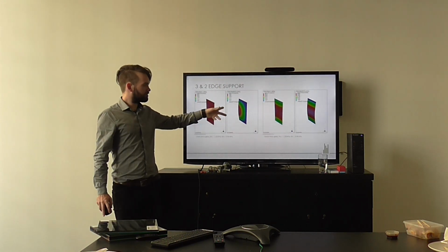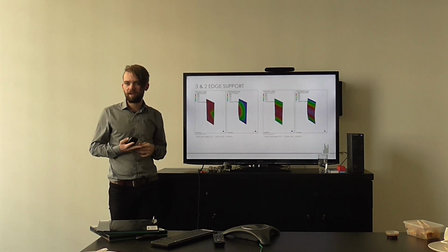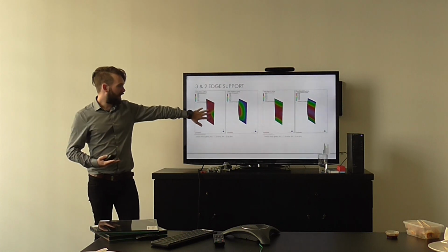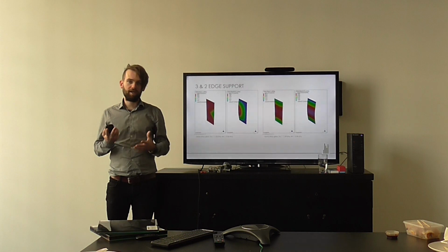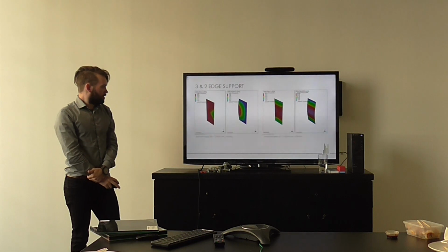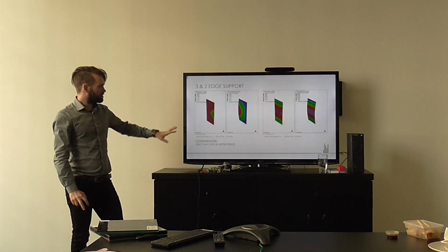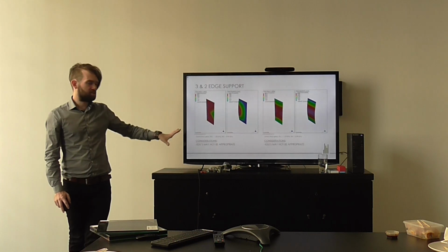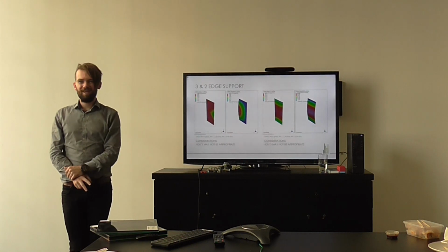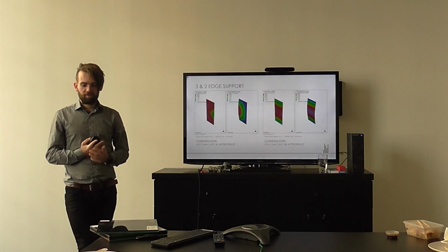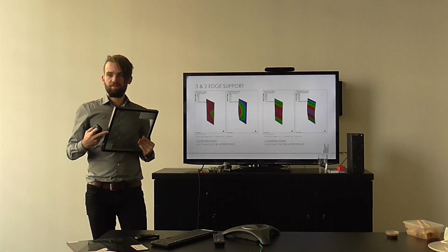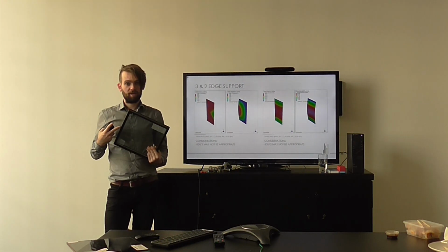The next one we move on to is 3-edge and 2-edge support. Now, these situations come up more probably in your lift lobby kind of areas, usually at a corner junction where you don't have a corner mullion, or you don't have, in this case, glass fins, and you want to read floor to ceiling glass. So what the considerations are here, we'll start with the 3 edges. In both of these situations, IGUs, meaning insulated glazed units or double glazed units, triple glazed units, might not be appropriate, because what we really need to do when we use our IGUs is make sure that the deflection along the edge is not too significant. It needs to be quite tight.